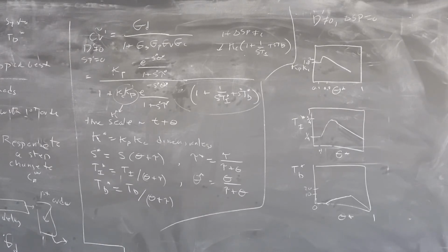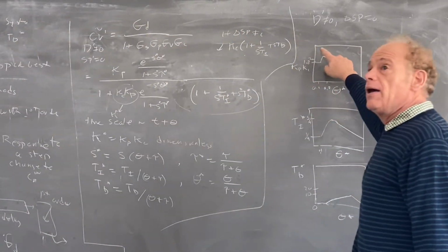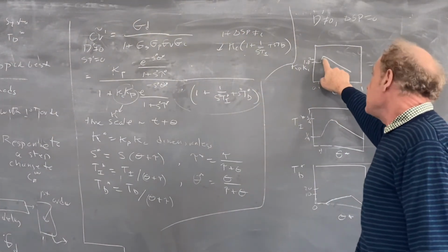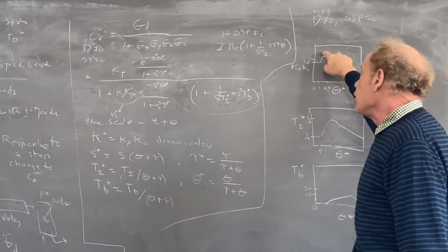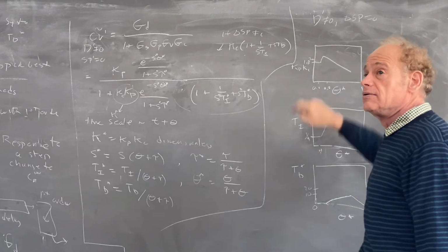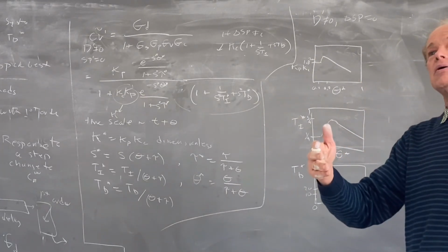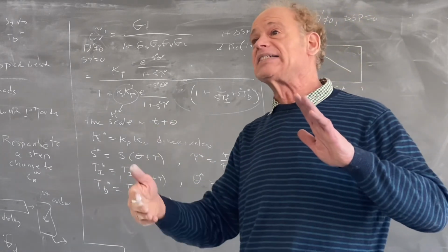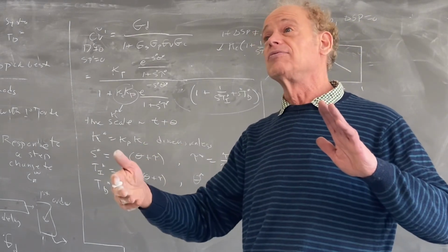Obviously, I don't want to get too aggressive, because then I'll make it unstable. But this rises almost instantaneously. This is the region where I don't trust the model. But once I start trusting the model, I want to go to a high value of KC. As the delay gets bigger, the system becomes less stable. So I'm afraid to be so aggressive.